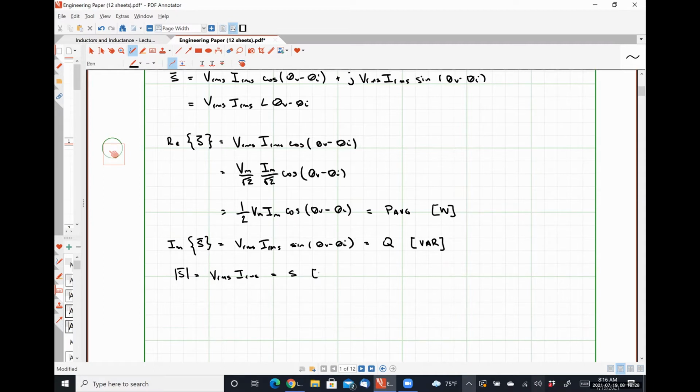Apparent power is measured in volt amperes, and this is the typical design constraint for a system, because this really represents the maximum amount of average, so I hate to say the maximum amount of average power because that's not really true. It's also not the maximum amount of instantaneous power, but it's kind of like the maximum amount of steady state power that you could possibly ever need.